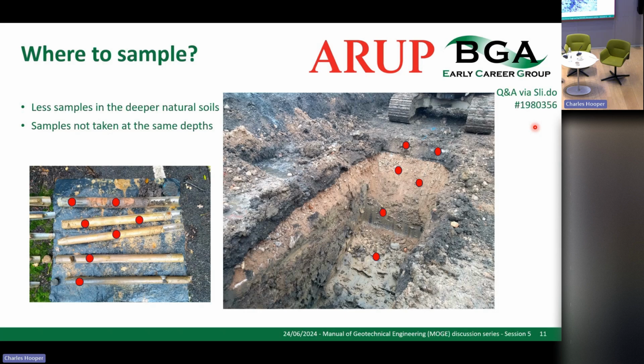For the trial pit, though, on the other hand, depending on how many positions you might have in this area, in this one, we only had a few trial pits in this area, so we took 2 samples from that upper made ground, so we'd have a little bit of variance within it, and then 2 samples of the deep made ground. So we've gone up to 4 samples with that to give much more information for what we're really interested in looking at, that upper part where we would expect there to be contamination. In the underlying clay, we've still got a couple just to provide that coverage, see if there's anything spread around.